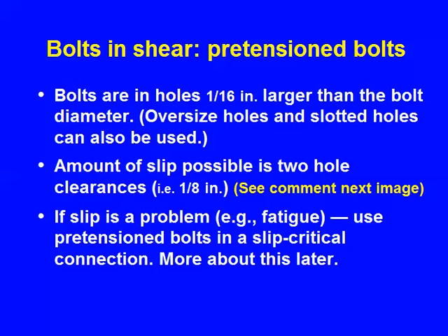Now, the amount of slip possible, if you sit down and figure that out, is 2 hole clearances. So 2 times the 16th, we're at an 1/8. So it could be 2 hole clearances of slip. Is that a concern for you in your structure? You may be able to answer, no, it's not, or yes, it is. I'll try to give you a little more background information, so we'll come back to that.